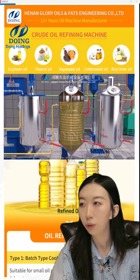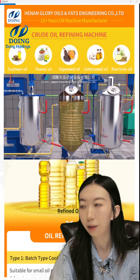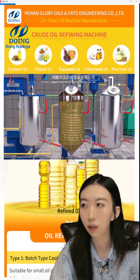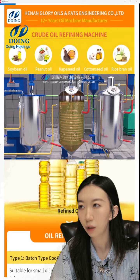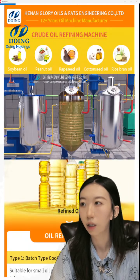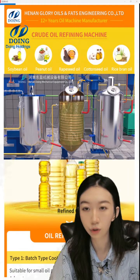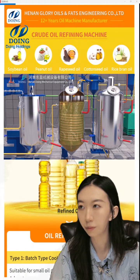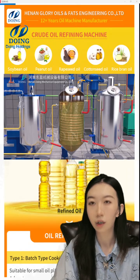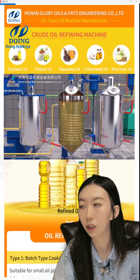The crude oil is pumped to the decolorization tank, and before decolorization, we heat the crude oil to remove internal moisture. During decolorization, we use active clay as the decolorization absorbent.